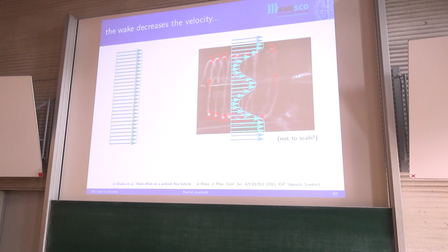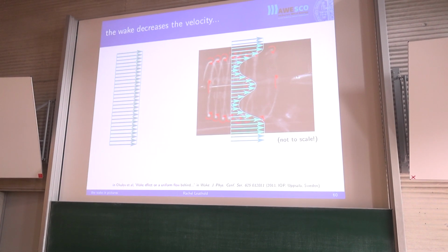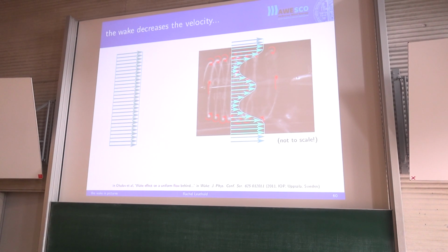So if we enter in a uniform free stream velocity into this field, then we see that there's a velocity deficit, where the flow is getting pushed back upstream slightly on the inside of this wake, right? And again, this is a sketch, so not to scale, but you can see that near the edges of the wake, where you do have the circulating motion pushed inwards, you would have the velocity decreasing in the downstream direction. And then at the center of the wake, where there's no circulating velocity component pushing the wind back upstream, you see that you get much faster wind again, okay?